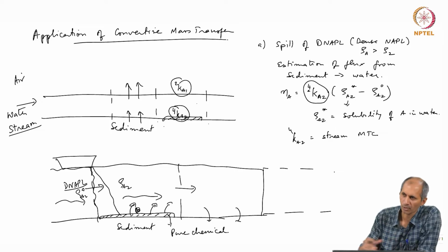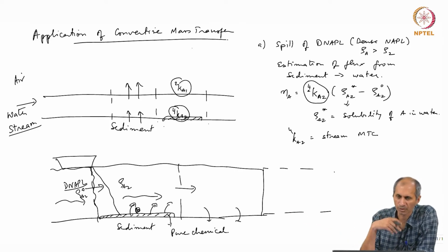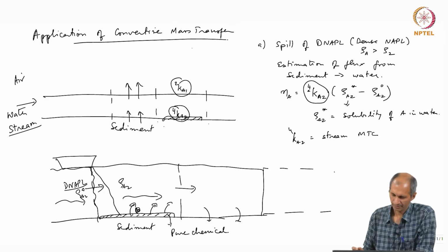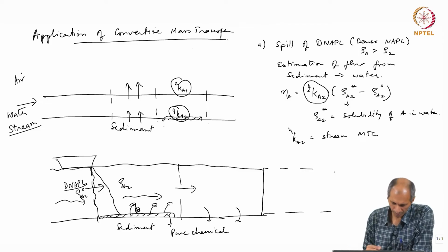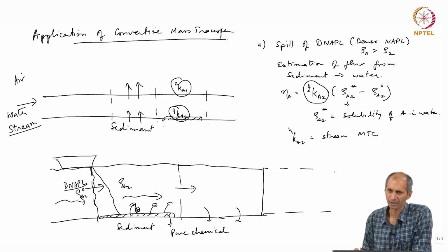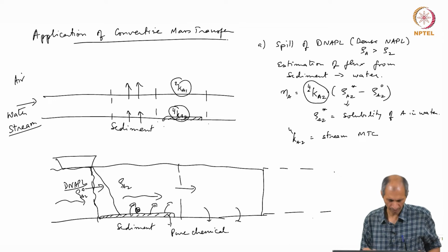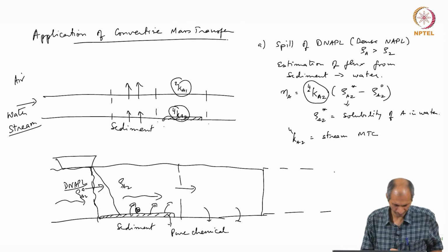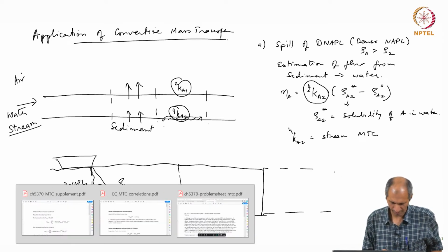It is a body of water that is moving over sediment. This is air which is going in whatever manner that is. Okay. So the problem now becomes, this is all it is, the equation is fairly well set. So the problem now becomes the selection of the mass transfer coefficient. So we will look at a set of mass transfer coefficients that we can look at,